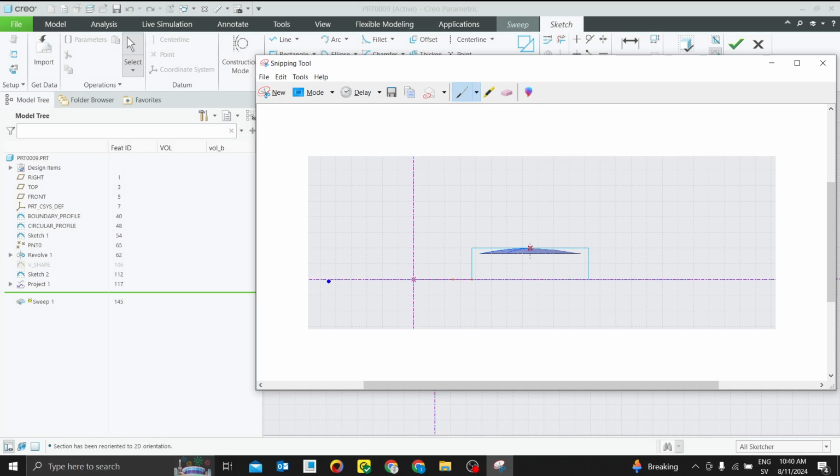This is the top plane here. This is the top plane, and I'm saying normal to projection. Therefore, as you sweep around the path, the profile, the cross section, will always stay normal.